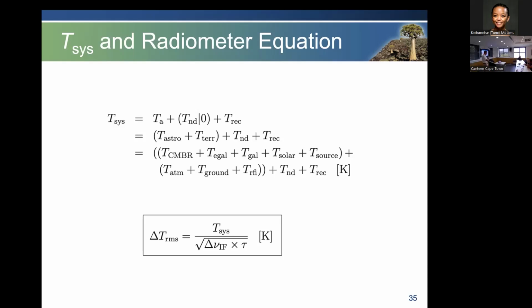In the digital route, you had a digital integrator where you added numbers together, quite literally. If you want to get a smaller RMS value, that fluctuation, because that fluctuation is the actual noise in your signal, you have to have wide bandwidths and long integration times, both of which cost you money. The one is a technology issue. The other one is just that you have to run the telescope for longer. And maybe your source doesn't allow you to do that.